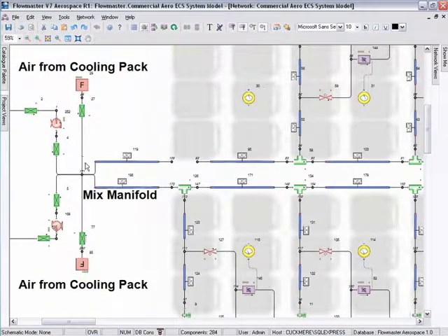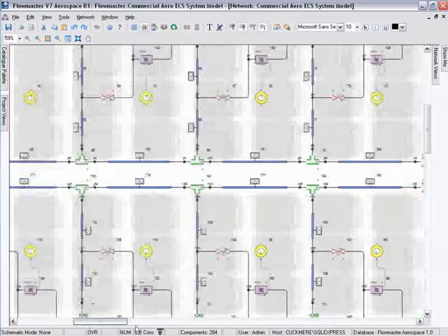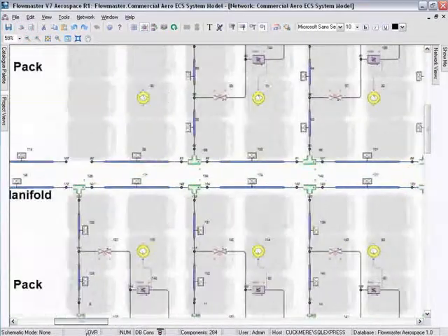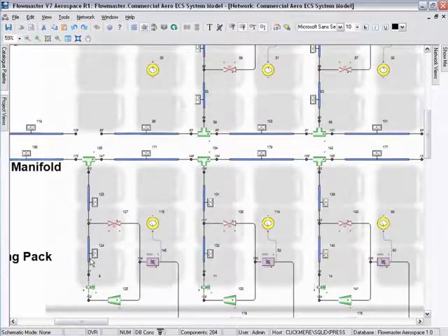Air is then supplied through the cabin, through these overhead ducts, which pass through the whole length of the cabin to the end, through some ducts, and then either pass into the cabin through this ball valve, which represents a Gasper valve, or through constant airflow down the side of the cabin through this orifice plate, then transition.